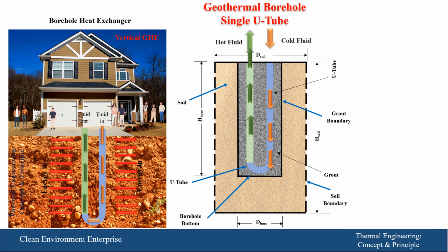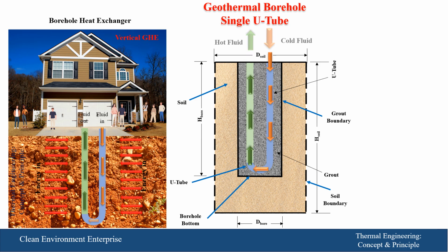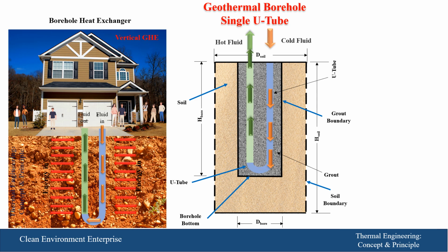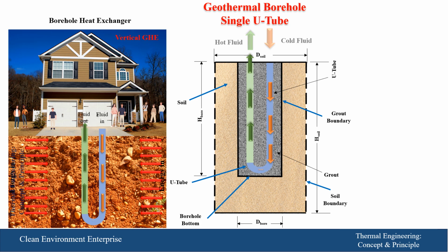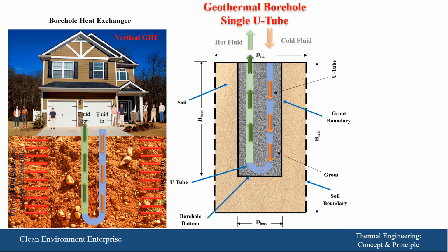It is composed of a U-tube, and the U-tube is installed inside a bore, surrounded by grout material, and this grout material should be a conductive material to facilitate heat transfer and conduction between the soil, the external part as shown in this figure, and the tube itself.